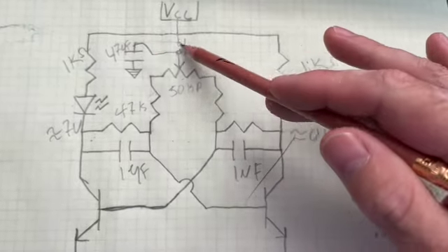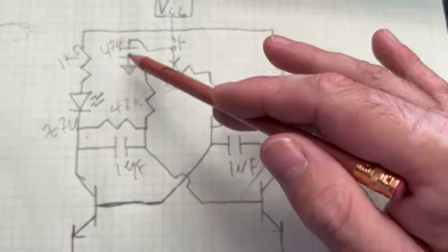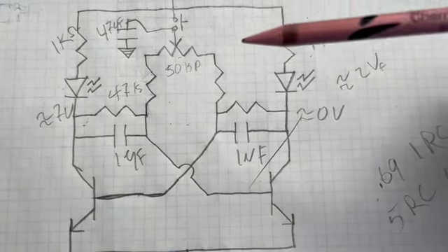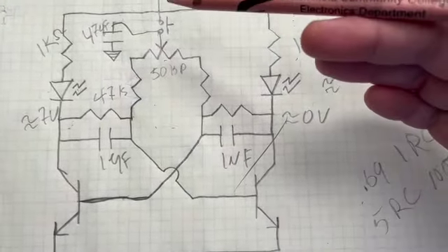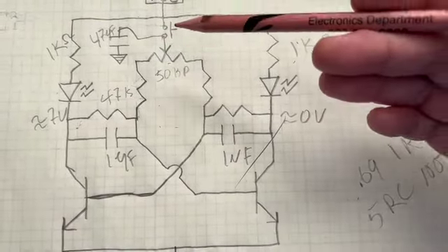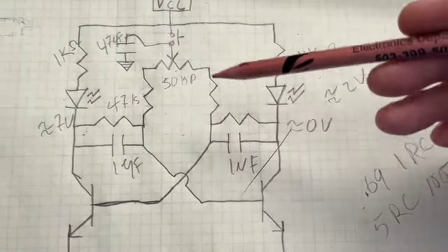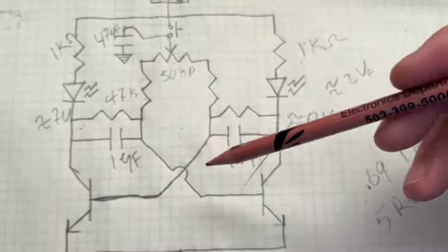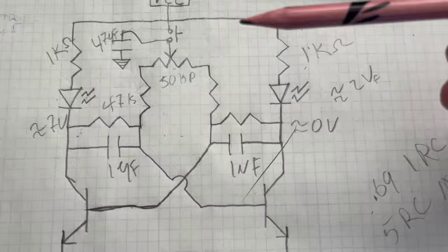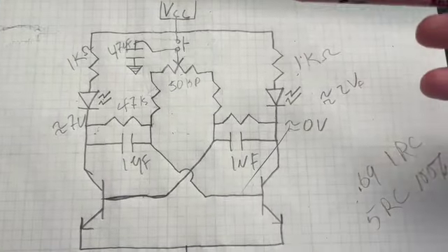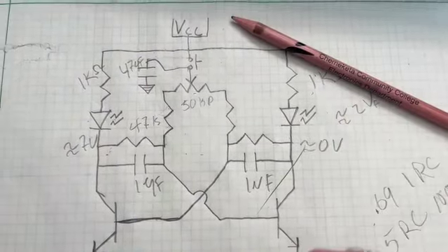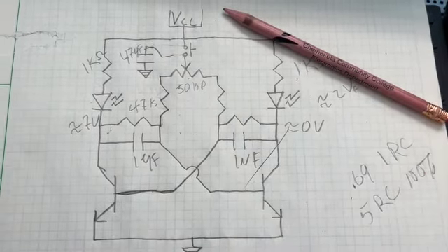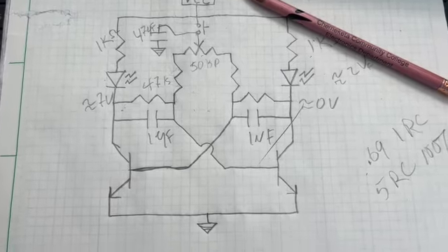So you see why the LEDs turn off and on. You see why there's that delay here when we let go of the button. This capacitor has to discharge through here, which is essentially the same thing as increasing the resistance, right? Until it becomes infinite and no current to charge the capacitors, nothing to allow the capacitors to discharge through. It becomes a stable state. And that's it. Everything that you need to know about this circuit to be able to build it and play with it yourself.